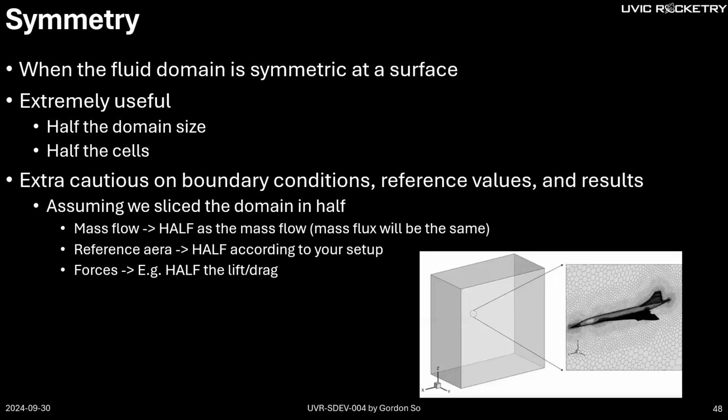But maybe your rocket is actually not rotated properly. But who really cares at this point, right? So you didn't make an assumption of where it is symmetrical. For a rocket, usually you use this one because it's more obvious. You capture 2 fins, and the benefit is that your flow would be aligned to your reference frame. Because usually a rocket reference frame is aligned with the actual fin, or one of the fins. So you want to capture at least one full fin.